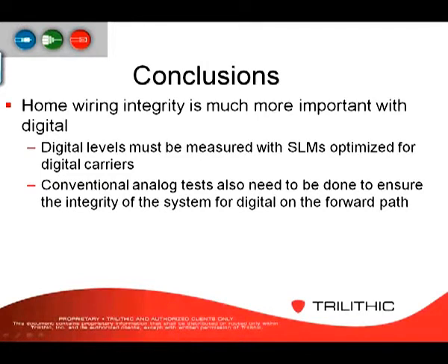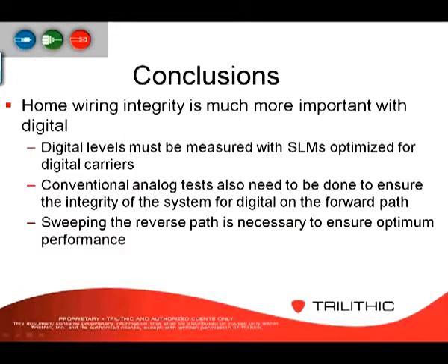Conventional analog test also needs to continue to be conducted to ensure that the integrity of the system for digital on the forward path is going to be successful. So still look at your carrier to noise on your analog channels, your other distortion measurements, whether that's composite triple beat, the CTB, or the CSOs, and so on. And then also your signal leakage and so on.